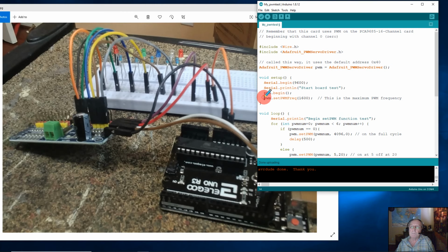Then you set the pulse width modulator frequency. You can adjust this frequency up and down, and it's just like 50 hertz, 60 hertz. Right? We use 60 hertz. Europe uses 50 hertz. Some devices talk different frequencies. Like if you're talking to a servo motor, you probably set that frequency all the way down to 60 to represent 60 times a second.